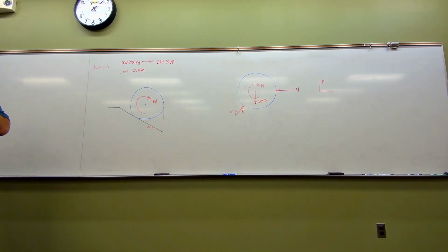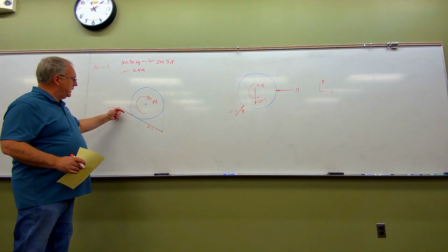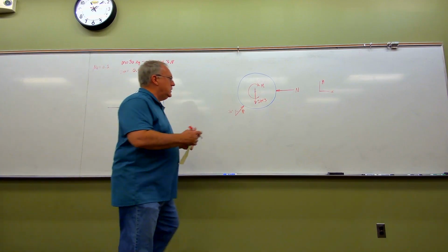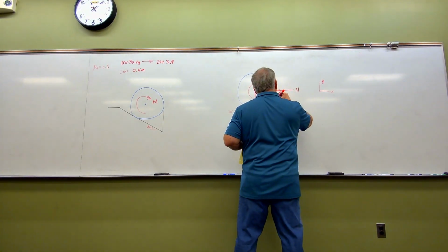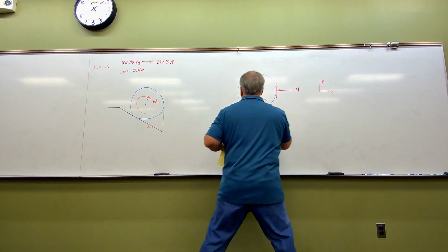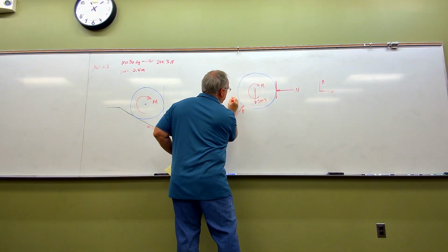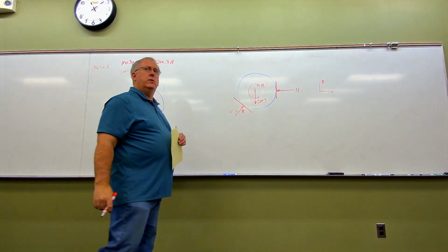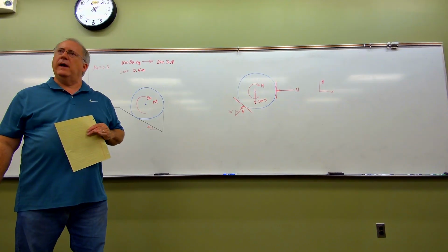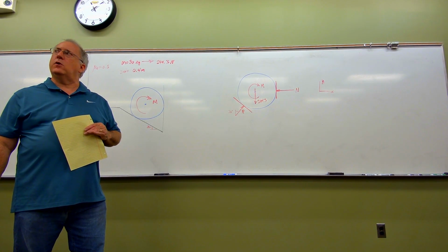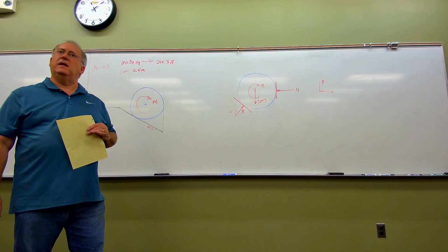And now the only thing we got to add to this free body diagram is our frictional forces. And we know that the frictional forces are going to exist along, collinear with the plane of contact. So I'm going to have a frictional force over here. I'm going to have a frictional force over here. And I need to include the arrowheads, contemplating the directionality here, where these arrowheads are going to oppose the impending motion.